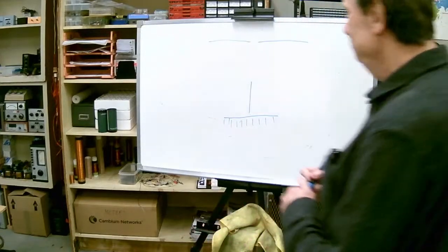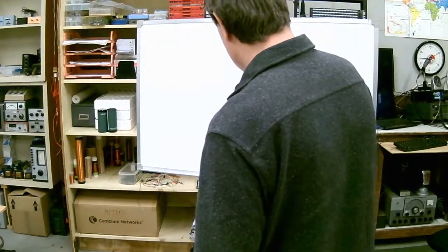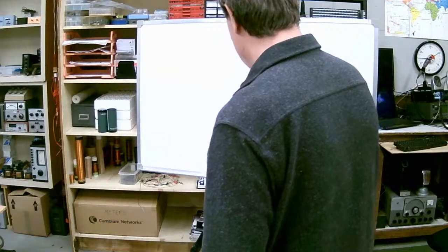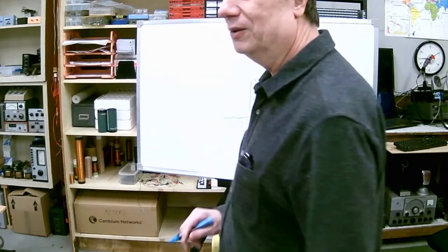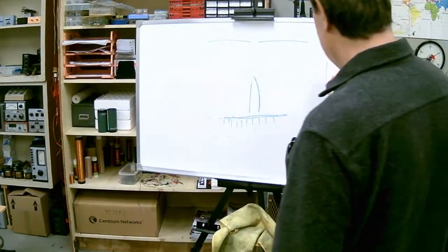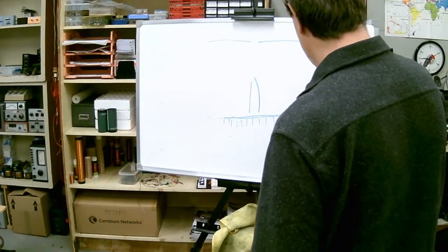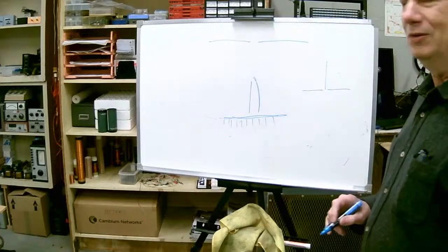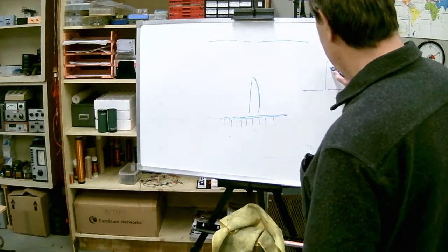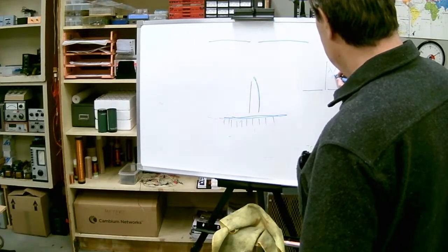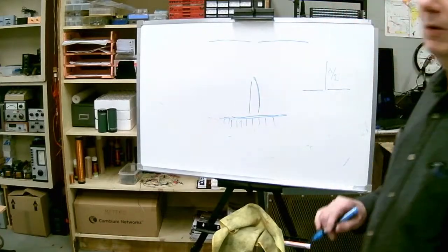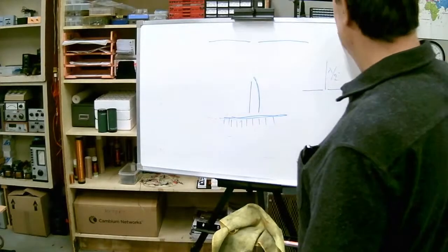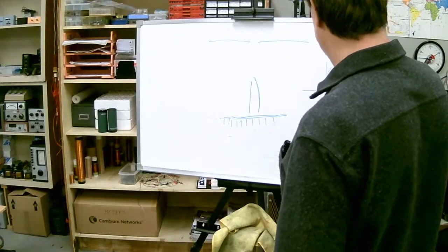So anyway, the Marconi antenna is a quarter wavelength long, and the other half of the antenna is this ground radial. So we can actually replace it, just for the safety argument, with two radials here. And the radiation resistance of a Marconi antenna is half of the dipole, so it's 36 ohms.